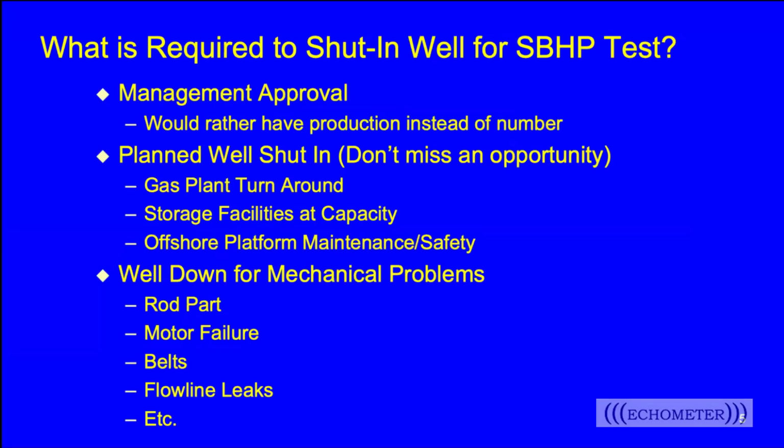Perhaps there's a motor failure, or the belts are down, or there's a flow line leak, or any other number of situations that cause the well to be shut in. Let's take advantage of these and get the static bottom hole pressure.